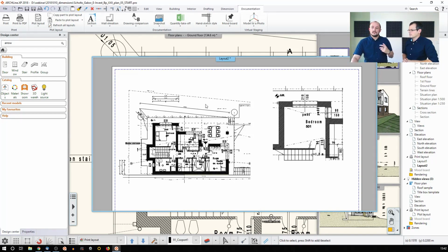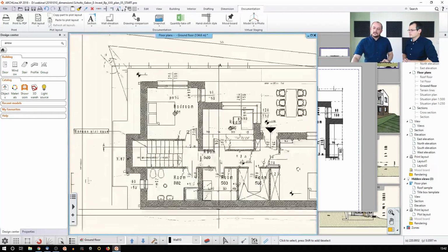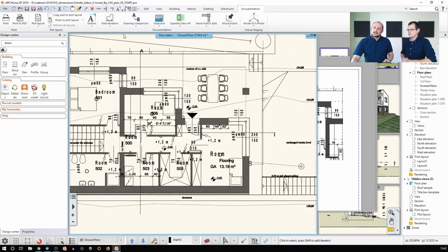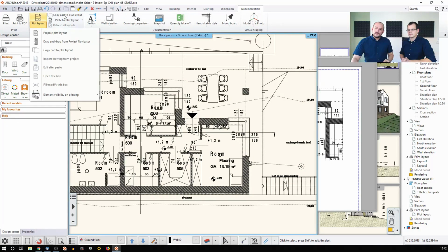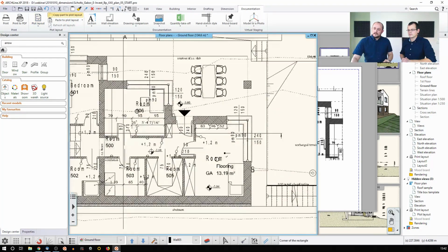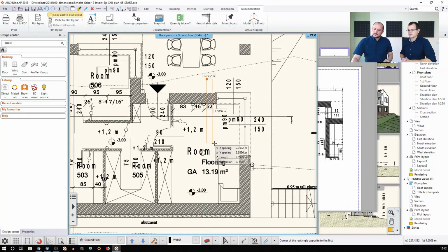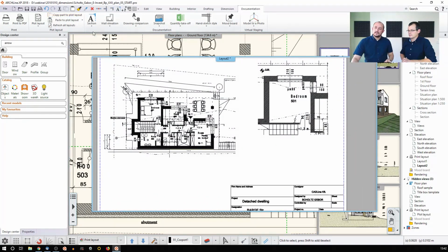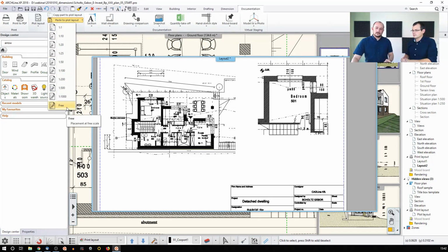And to complete this cycle, let me show you a third way of pasting things here, and that's when you have already decided that you would like to insert one specific detail of that drawing. Let's say I'm about to copy a part to the plot layout. Now I'm selecting this corner, picking it up with that corner point, and then coming to this one and saying, okay, just paste it here in any of these. Or I can actually just pick and type a certain value as well.